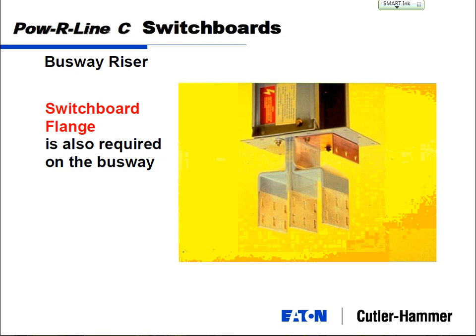Each inch of cable is going to lower the voltage just a little bit more until you get up to the top. Busway has a fraction of the voltage drop that cable will have, because busway is really a continuous bus bar running all the way from the floor to the top.